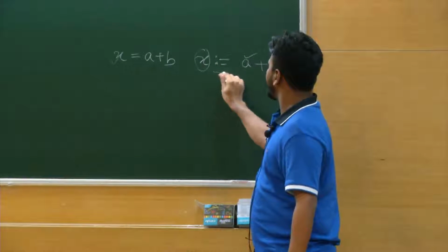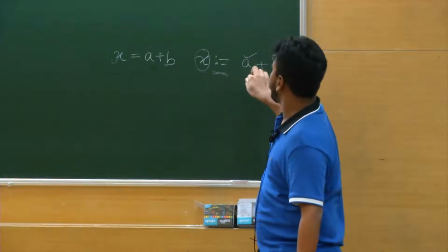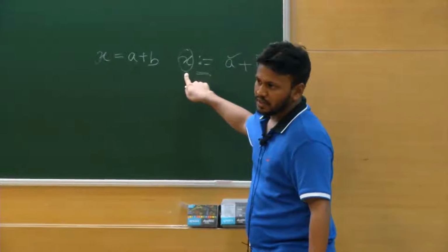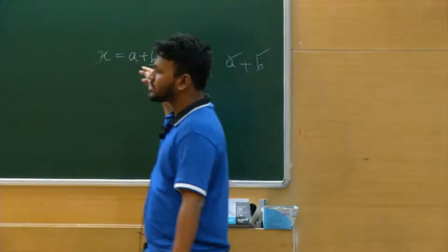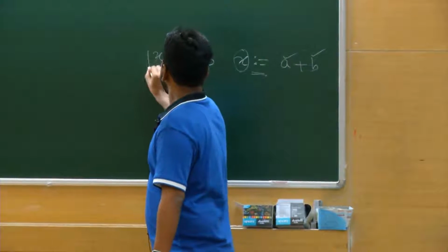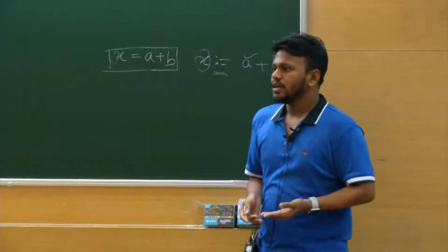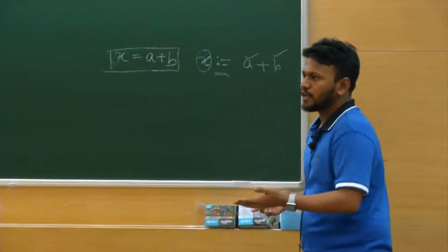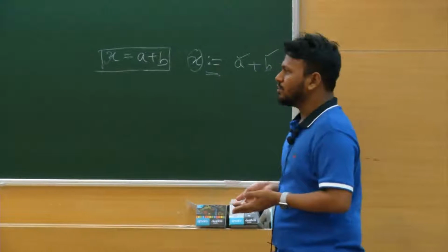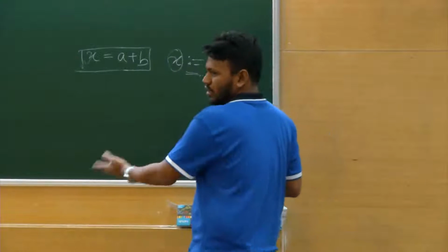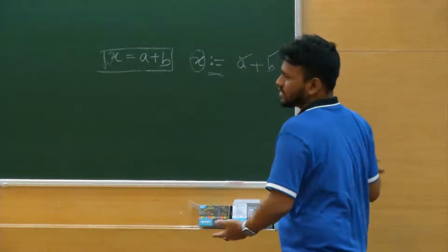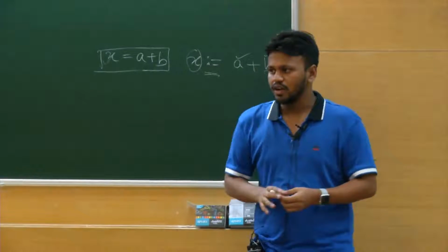So this is basically an assignment, where A and B must be known and I'm computing C, which is not what OpenModelica does. OpenModelica follows an equation style where I can just write the equation irrespective of my known and unknown variables. In an algorithm, I need to specify what is known and what is unknown, always having the unknown on the left side and the known on the right side, which is not the case with Modelica.